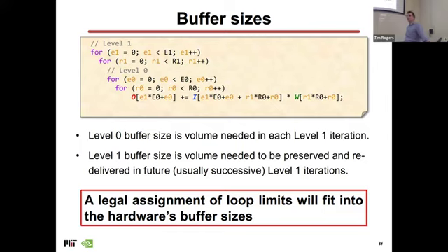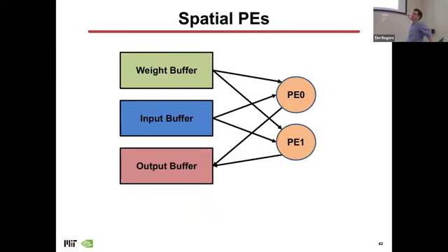Okay, caches are there because, well, we don't really know where you're going to go. General purpose CPUs and even GPUs can run any program. You've got to make sure that it runs sufficiently well. But if you just know exactly what's going to be accessed, there's no point in having a cache. You should just use scratchpads. And most of these do this.